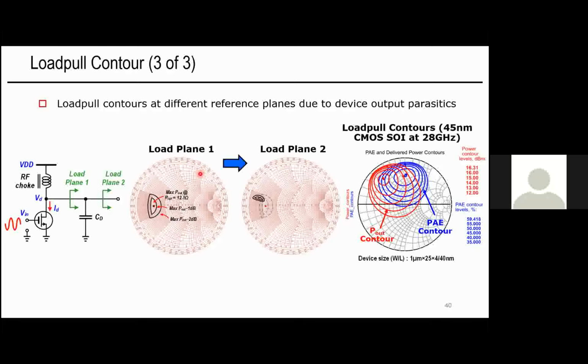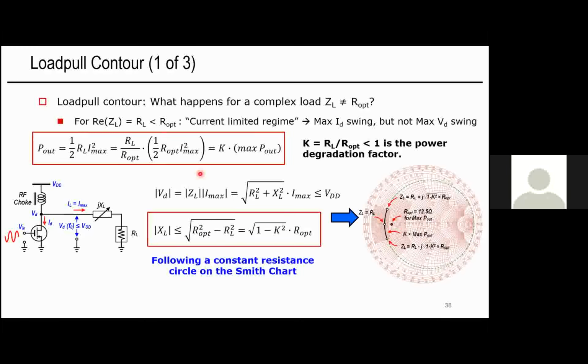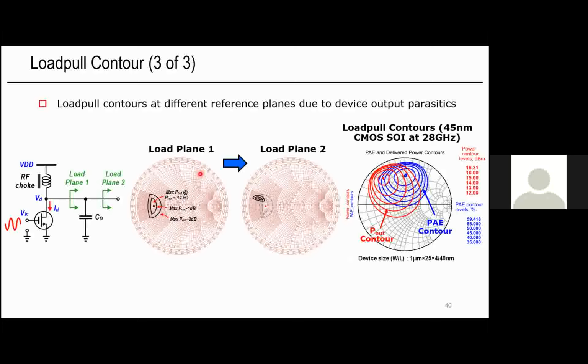Professor Wang, a consideration about how we measure stability. In the slide that you presented, it was measured with K. Of course, it can also be the mu. They're interchangeable. But is that enough for power amplifiers? Because as far as I'm aware, K or mu parameters, either one or two, are indeed necessary conditions for stability, but not sufficient. For example, we might need to add another one like the determinant, S11, S22 minus S21, S12. Is this relevant, or is it enough?